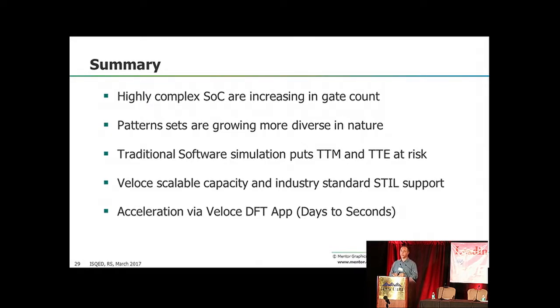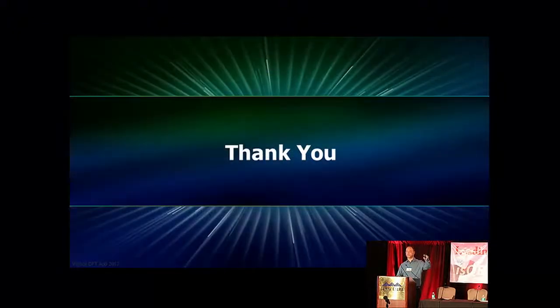With Veloce, we've got the gate count, and we've got the performance. We support the industry standard STIL pattern format, which any tester can read. It doesn't matter if you're on a Teradyne or an Advantest, any of the testers can read STIL. And it's days to seconds emulation. Thank you.